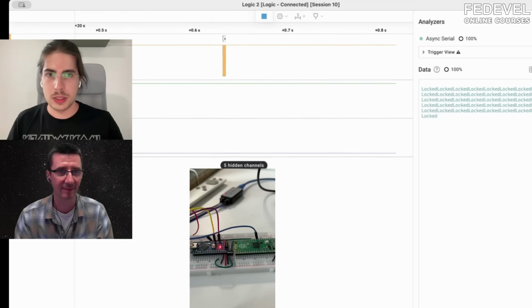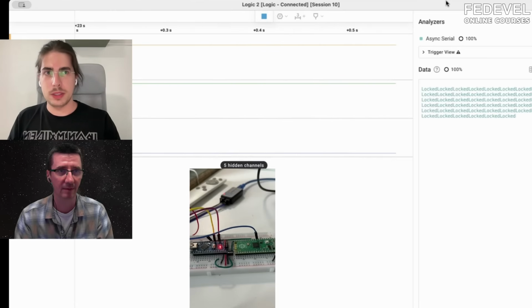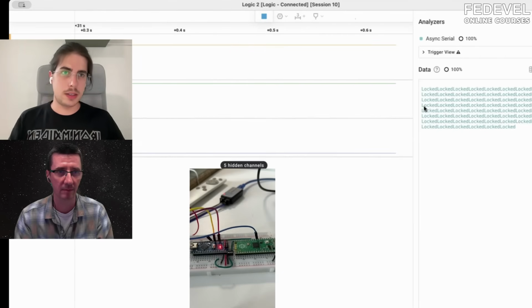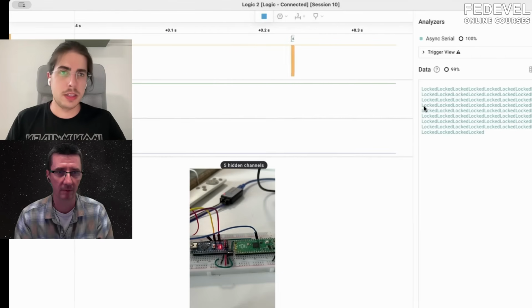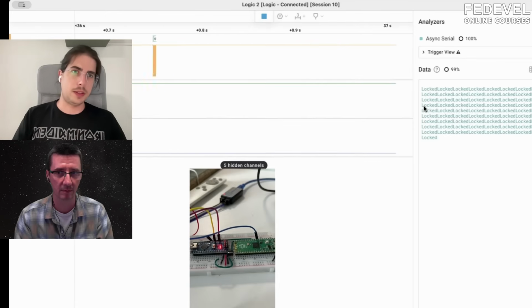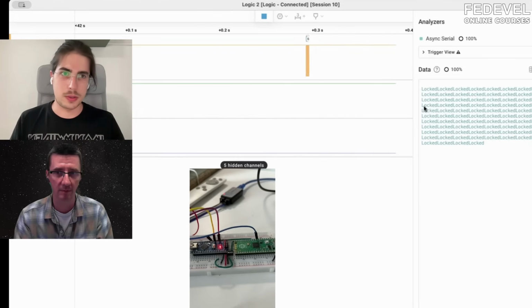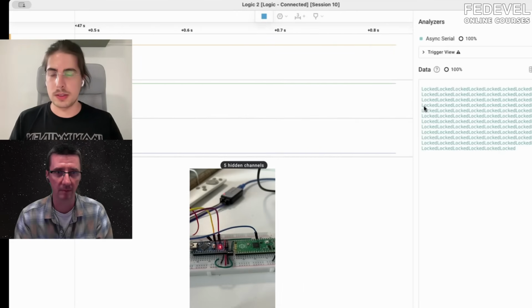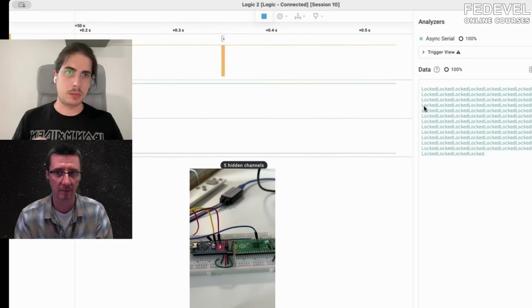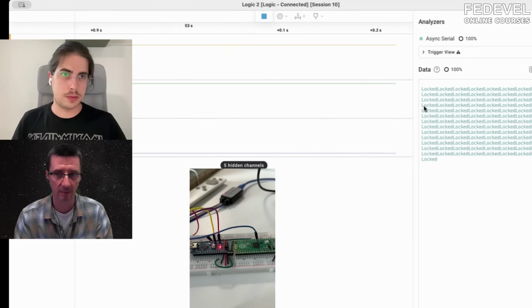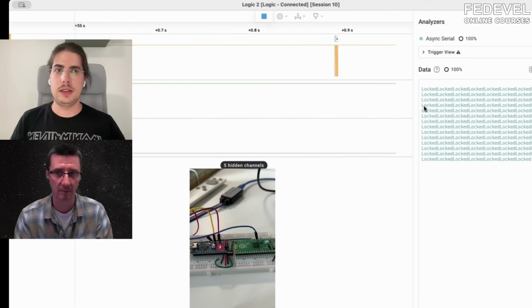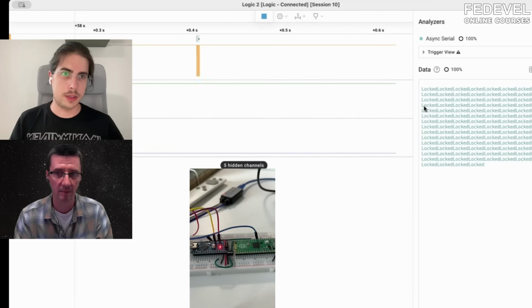So what we see here is also a possible attack against real firmware, because sometimes they are locked in a state like this, where it's an infinite loop. Even if there's no counting, if you can jump out of that loop, then you maybe get access to some hidden functions like a console or internal settings and stuff like that. So it's not uncommon to lock users out by just sending them into an infinite loop in a production firmware, meanwhile keeping critical parts of the code in the firmware.